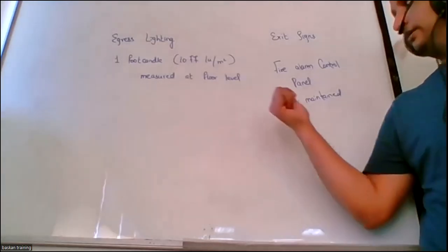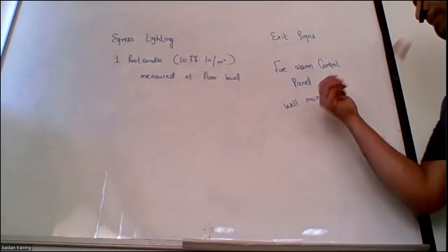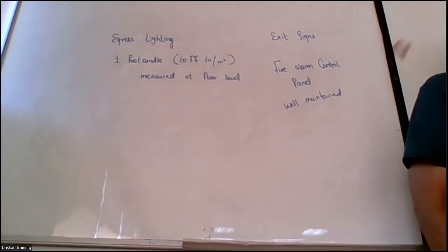So that is why the first component of our alarm control panel that you have to check is the batteries. Usually when I go for maintenance of control panels, the first thing I do is cut off the power supplies. The authority power I cut off. I do all my testing on the batteries, because your batteries should be capable of carrying the load of those notification appliances, your sounders, everything. If it's not carrying, no use.